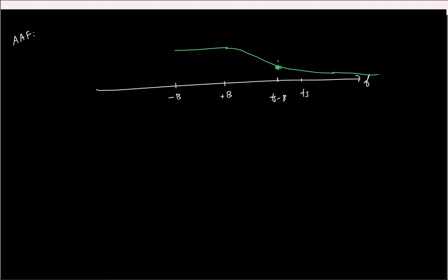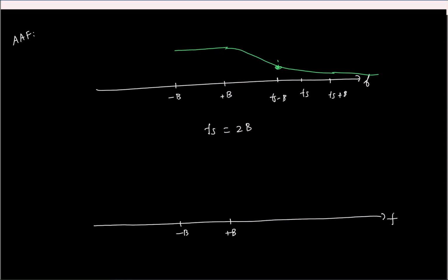Great. Now let us say I strictly obey Nyquist, because Nyquist was a smart guy. So I choose Fs to be 2 times B. Here the band of frequencies which can alias back is Fs minus B to Fs plus B. If I choose Fs to be 2 times B, what is the band that will alias back? Of course, the low pass filter must pass up to B, so basically I need to filter off anything beyond B. How should the characteristics look? It should basically drop immediately.